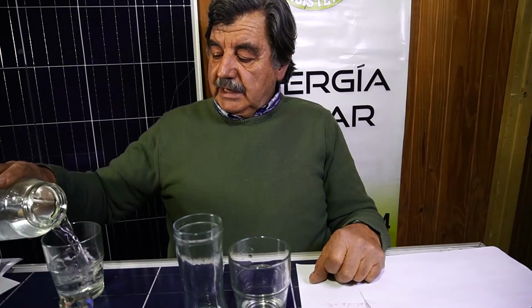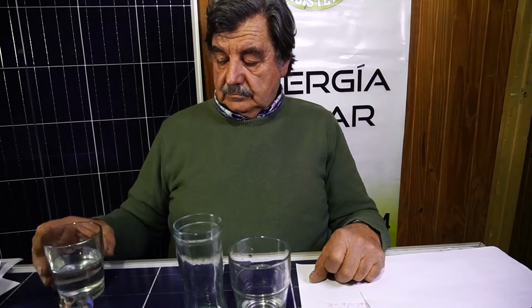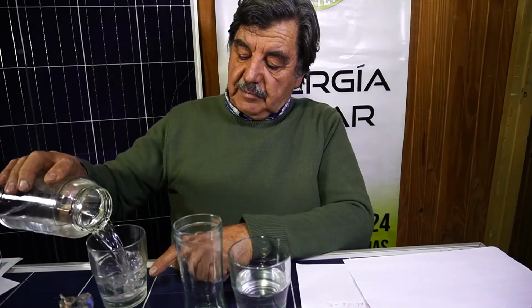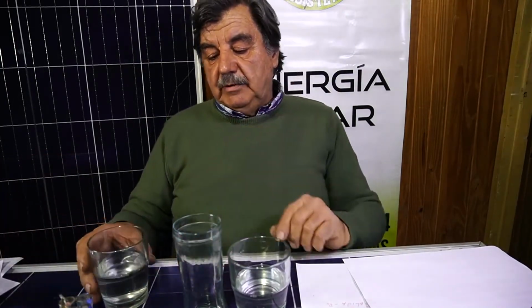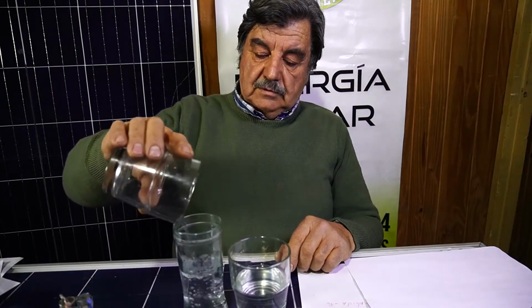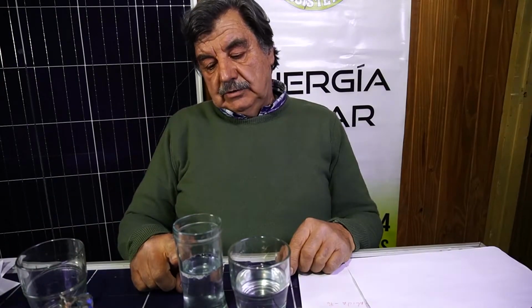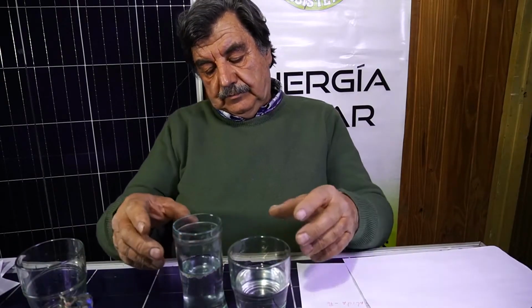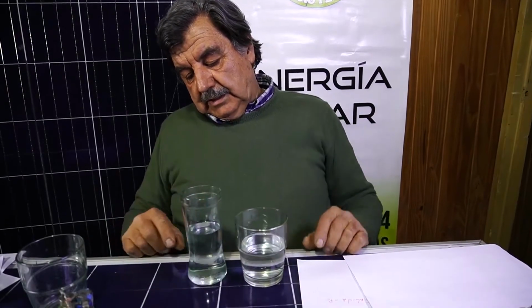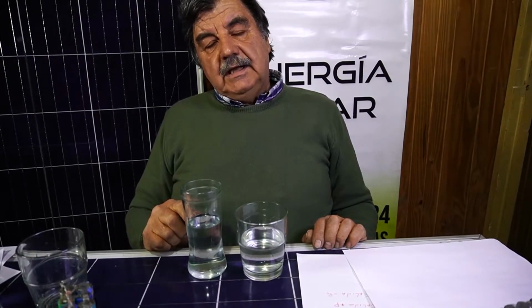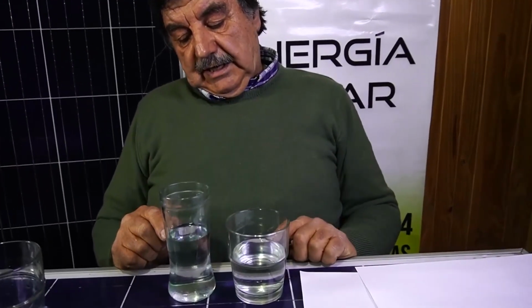If I put the same amount of energy into both batteries, now I'm going to add the same amount to the other, because it goes in parallel. Look what happened. This one reached the level above 4.2 before. To see it better, this one arrived before, even though it has less capacity. It arrived at maximum voltage before this one.